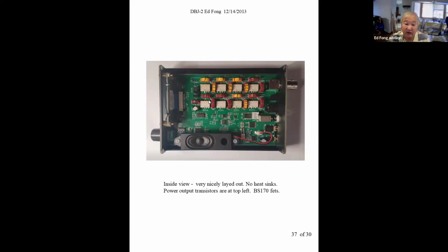If you ever want to hear a talk on how the principles of a switching RF amp work, I'll discuss it. It's not just simple switching like in a DC power supply, because it would demand to be so fast. At 28 megahertz, you would need a switching transistor at 200 to 300 megahertz. That's not practical. But he figured out a really clever way of switching this at a low frequency.